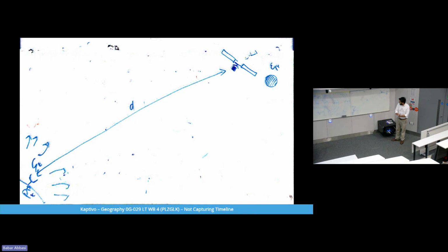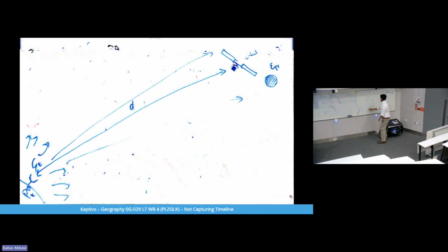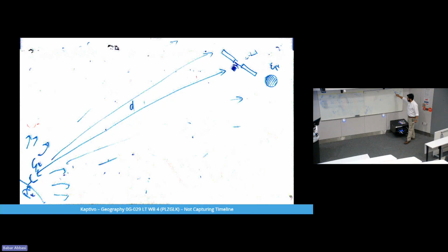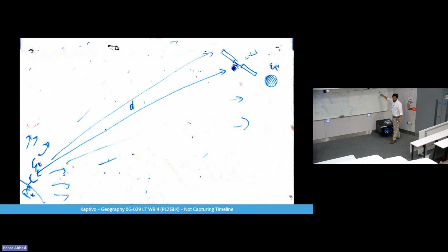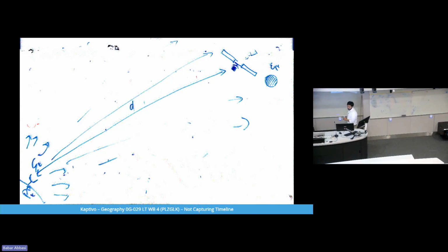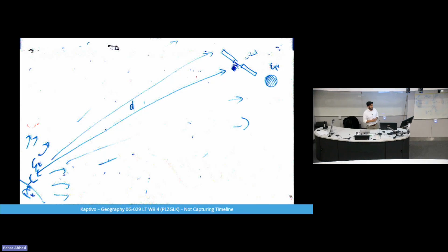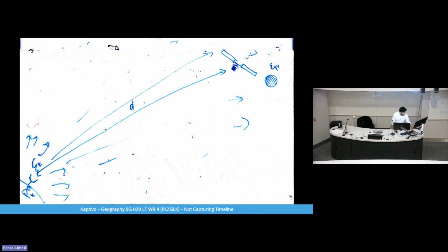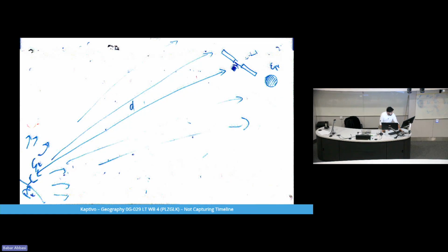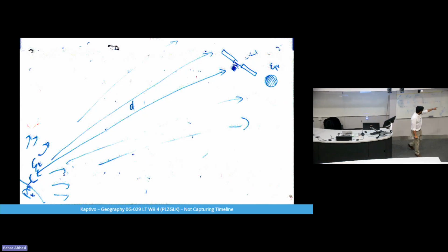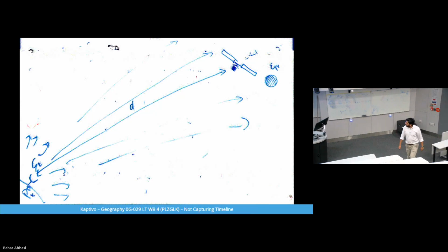The total power that is being radiated is spread across all different directions. There will be some energy going here, some energy going here, but I am only interested in this particular small little area, this one. If I want to mathematically write this whole example, I use the free space equation that will give me exactly how much power I will receive, and it depends upon the aperture area of the received antenna.